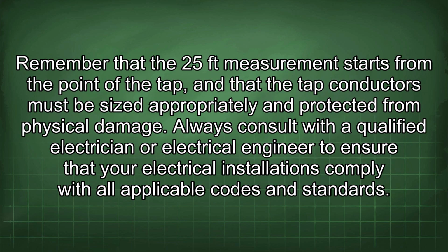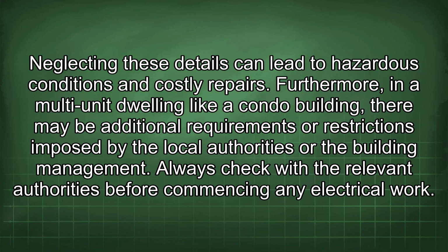Remember that the 25 FT measurement starts from the point of the tap, and that the tap conductors must be sized appropriately and protected from physical damage. Always consult with a qualified electrician or electrical engineer to ensure that your electrical installations comply with all applicable codes and standards. Neglecting these details can lead to hazardous conditions and costly repairs.